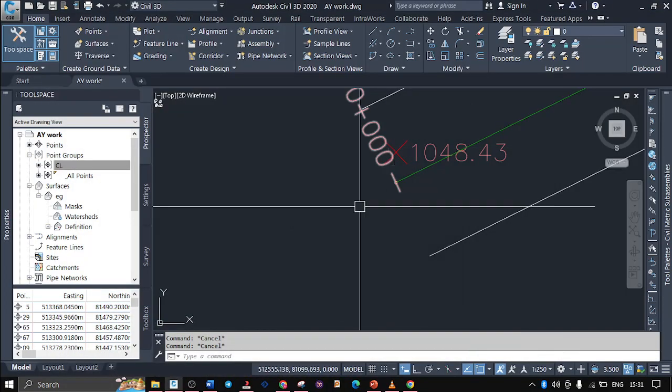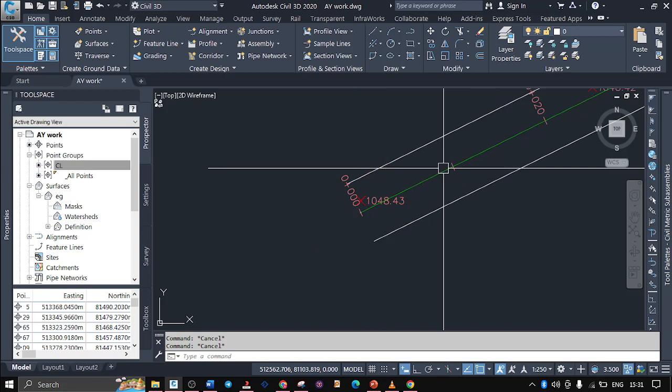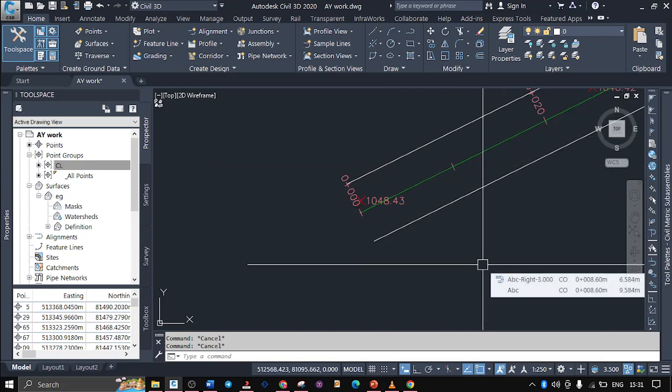All right. So now, when you design your new alignment, you are going to export a report that defines the alignment XYZ points, because the surveyor picked this point and you have proposed this point. What is the XYZ of this point here? What is the XY? We are going to export alignment coordinates into Excel such that the surveyor can set out those points.